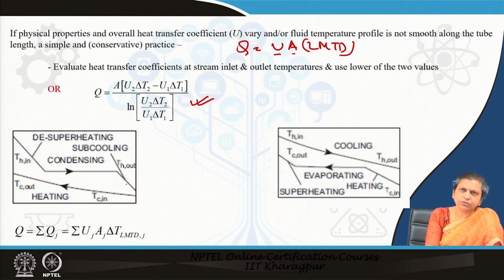So it cools down, then it condenses, and then the liquid again cools down. So, over this entire area it imparts heat and heats up the cold fluid. In this case, what will you do? How will you find out the LMTD? The same thing is applicable in case we are cooling a hot fluid by using an evaporating liquid.